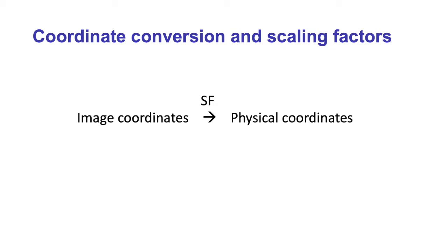To measure the displacement of an object from captured video images, the relationship between the image coordinates in pixels or pixel fractions and physical coordinates in millimeters or centimeters must be determined. Based on this, a scaling factor or a conversion ratio will be established.